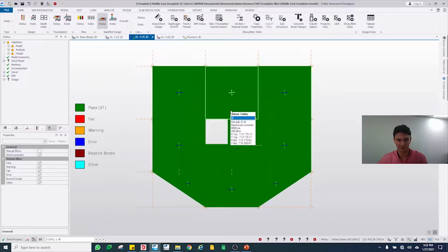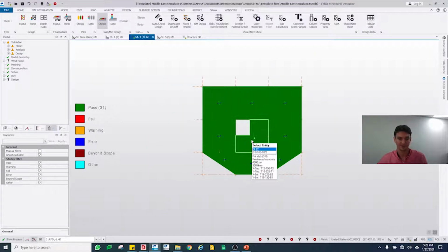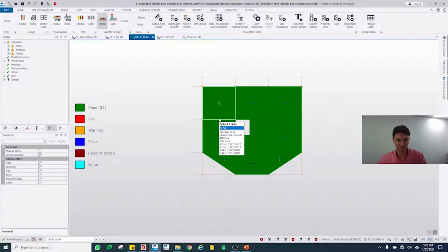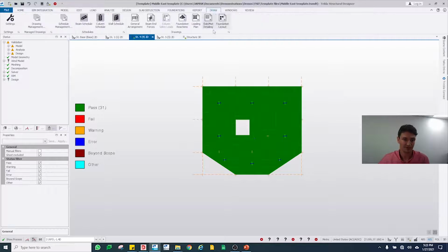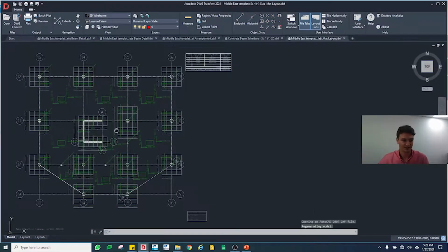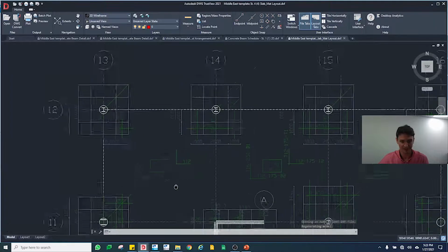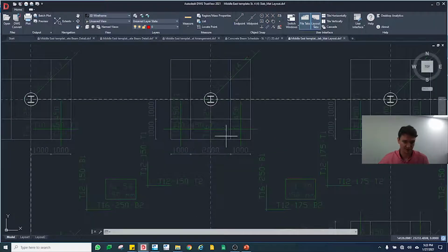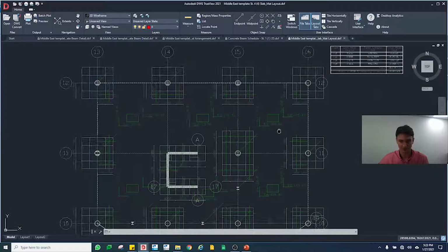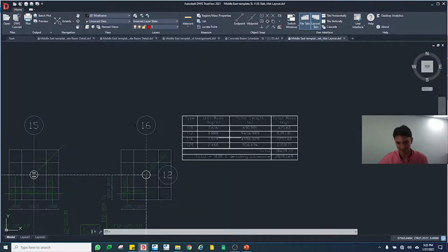And then lastly, just quickly, you can create some quick fire drawings. So as an example, here we have our flat slab with reinforcing and nominal reinforcing plus additional reinforcing in the strips. In the draw tab, we have these quick fire drawings you can see. So I can create a quick slab mat detailed drawing. Again, open straight up in AutoCAD. So here you can see the reinforcing top and bottom, both directions, the slab thickness, the reinforcing in the actual strips, and again the reinforcing types, masses and lengths on the right hand side.